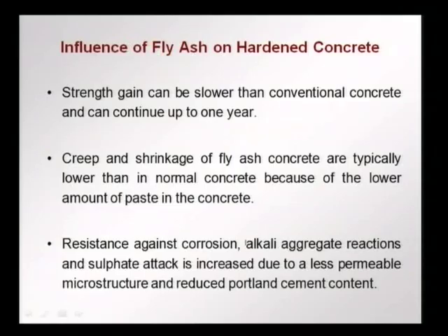Creep and shrinkage are typically lower than in normal concrete because we have lower cement paste, and also we find that because of this lower cement paste, less cement content, we have better resistance against corrosion, alkali aggregate reactions and sulfate attack. So, we get much better durability also.